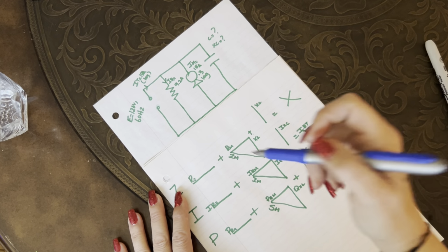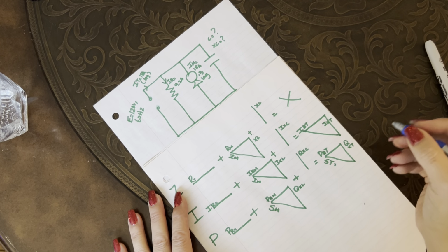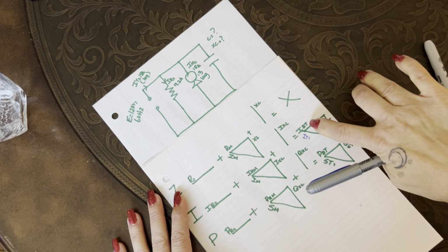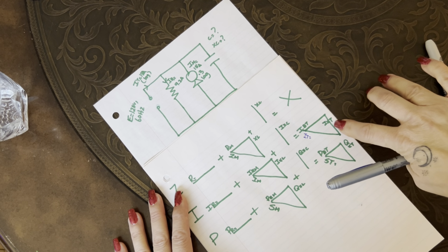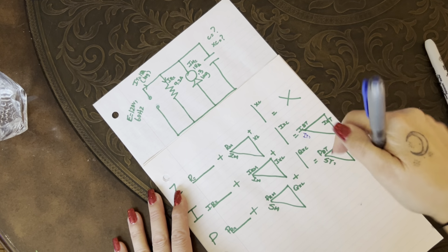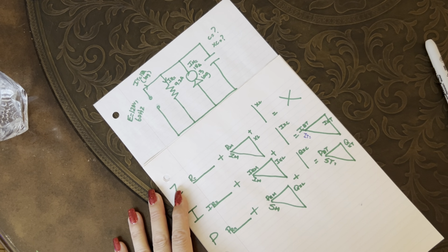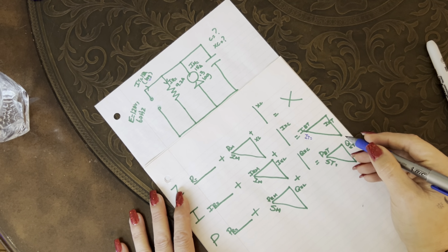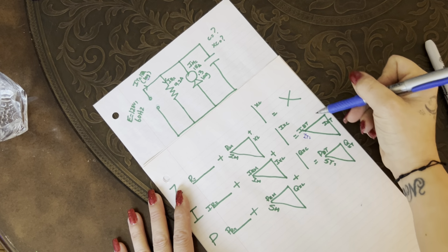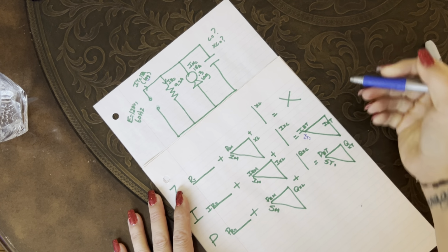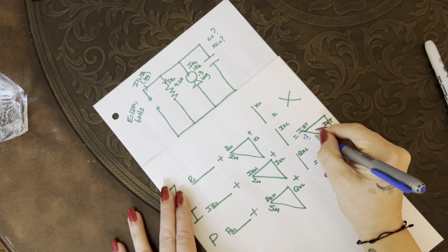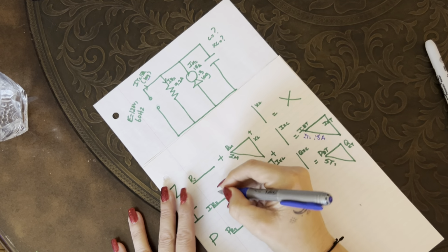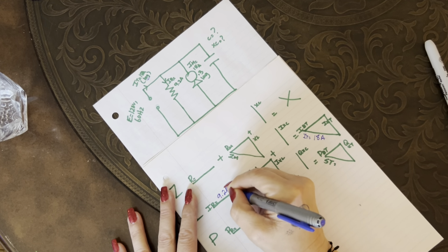So my incoming current for the circuit is 18 amps. That would be found here. That's my I total, right? So that's the vectorial sum of all of my in-phase current vectorially added to my IXT. I've drawn my triangle in the downward position because I know it's lagging because it told me it was, meaning my IXL is greater than my IXC, so that IXT is lagging. So my I total is 18 amps, so I'm going to put that in there. Okay, the resistor has a current flow of 9.2 amps, so that gets populated right there.